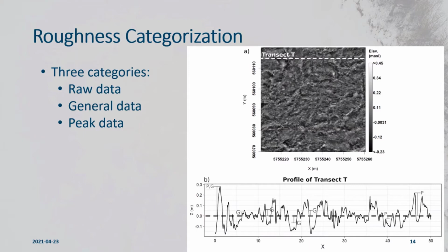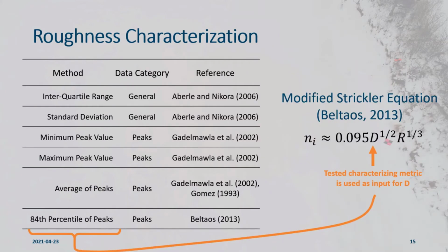So that's the same way if you're doing a pebble count in a river, you're looking at the D84, or sort of the largest particles in the river are dominating the roughness regime.